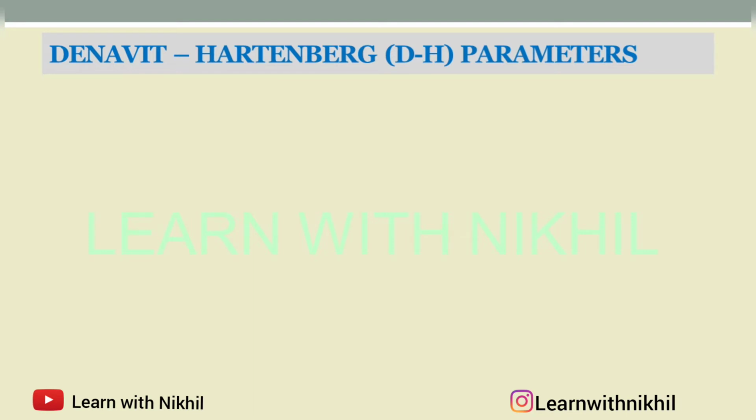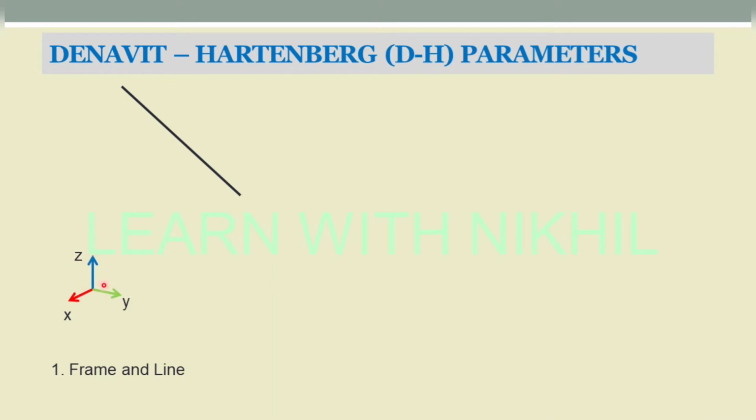So we'll see that. To understand the DH parameters, first we will understand the concept of frame and line. So I have this frame, this is the 3D frame, and we have a line which is in 3D space. This whole thing is in 3D space. Now I have to travel from this frame to this line. If I have to connect this frame to this line, the method is that in the first step we have to draw a line parallel to this Z axis. So we have drawn a line parallel to this Z axis.